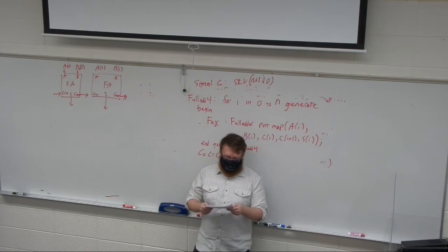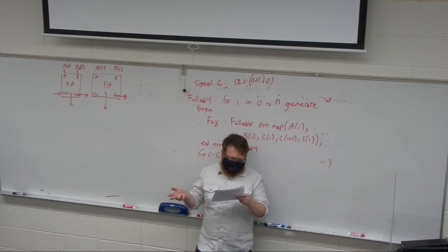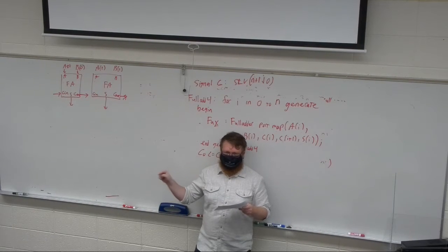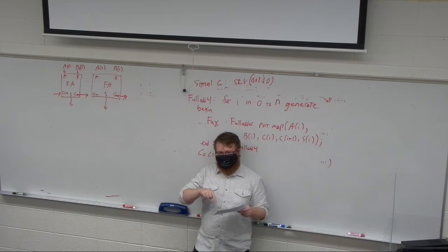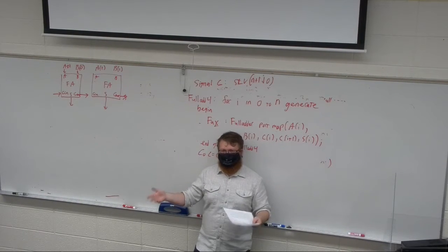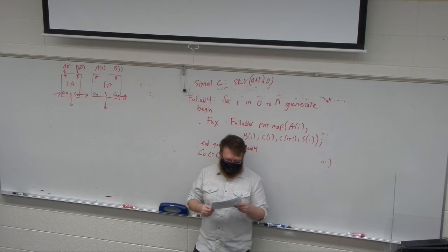Okay, so number 1, you guys got mostly correct. The most commonly missed one on this one was the fast carry adder was listed as sequential; instead it is combinational. You can tell that if you just flip to the page where it talks about the array multiplier, which is the most visible. The array multiplier is all combinational. Every other type of multiplier has sequential logic. The array one is combinational, which would make it fast and huge, right?